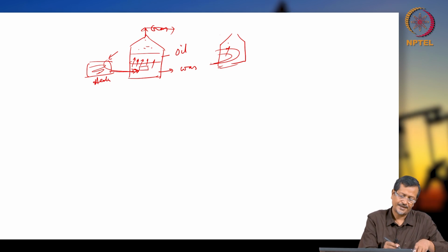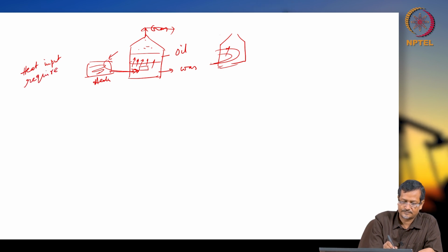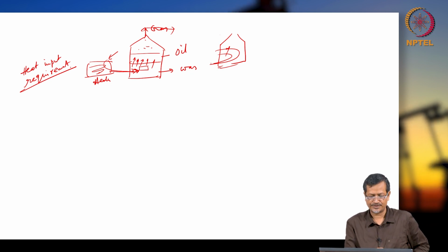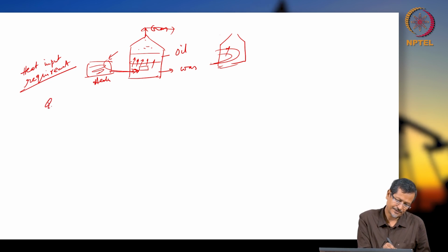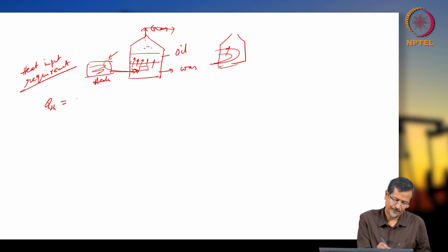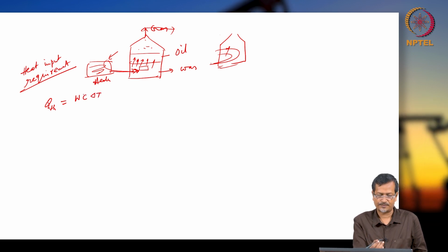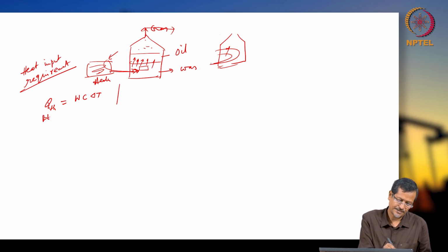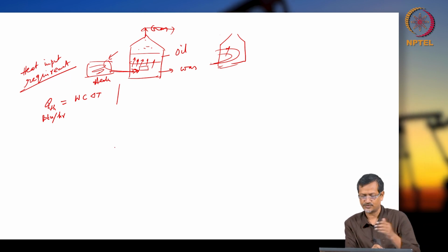So we will calculate the heat input requirement. How much heat is required to increase the temperature within the heater. The theoretical heat transfer rate, you know, is Q_th = W C delta T, BTU per hour. Instead of W you can put M also, the mass flow rate. Based on this formula we will be solving some problems, so maybe you can note down this formula.